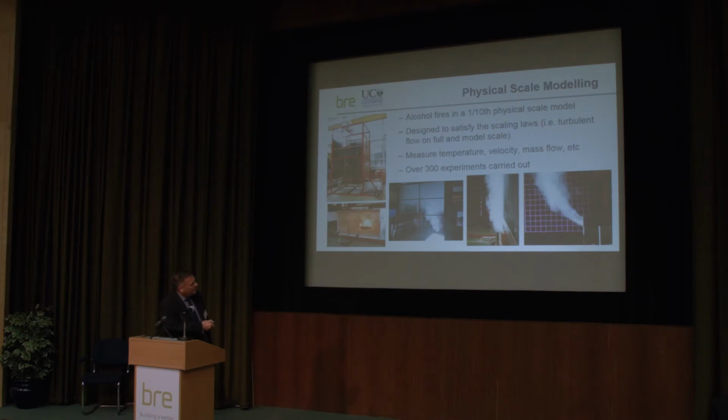Here's a photograph of an adhered plume. Here's our fire compartment, the smoke layer forming here, rising and adhering to the wall, and we've got entrainment occurring into the plume on one side. Here's the equivalent for a balcony spill plume. You'll see here, projecting, there's our plume, and we're getting entrainment into both sides, and in this case, into the ends. So it was a busy time looking at quite a number of different scenarios.